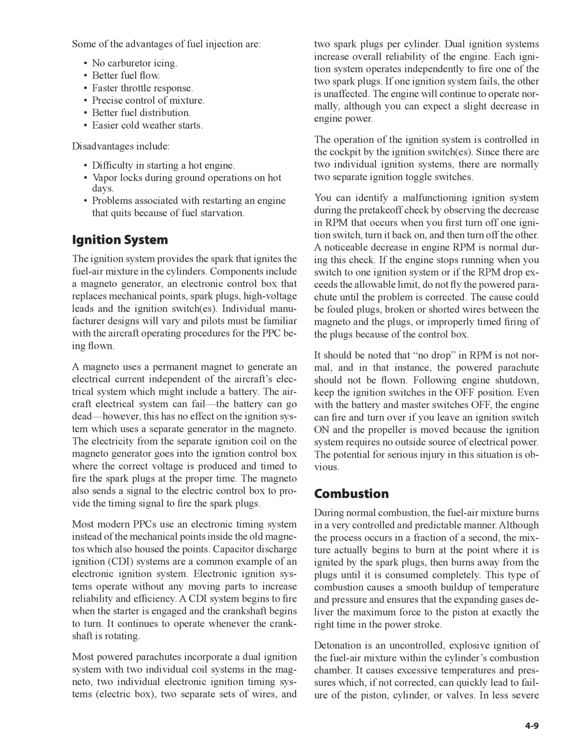Disadvantages include difficulty in starting a hot engine, vapor locks during ground operations on hot days, and problems associated with restarting an engine that quits because of fuel starvation.